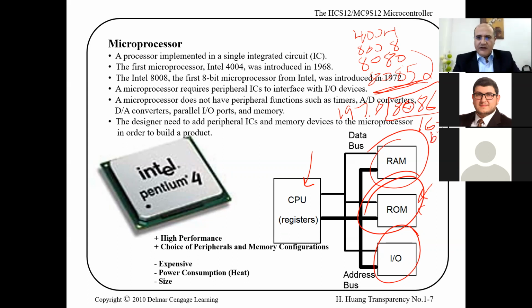Okay. In parallel, at that time, they did an 88 processor, 8086 and 8088. This was a big move from 8085 to 8086. They moved from 8-bit to 16-bit. At that time, the peripheral interfaces were not 16-bit ready. So they made an intermediate version, the 8088, that works from the inside as 16-bit, but it has 8-bit interfaces.